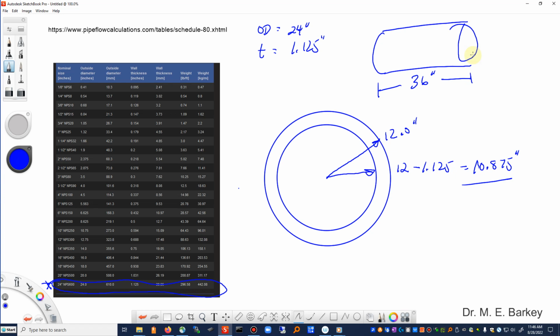After that, we're going to apply an internal pressure to our pipe and see what stresses we get with that. As part of this, we're going to verify our results with mechanics of materials, our deformation or displacement calculation of the end of the pipe, the change in length of the pipe, and also with our thin-walled pressure vessel theory. All right, well, let's get into Hypermesh first.